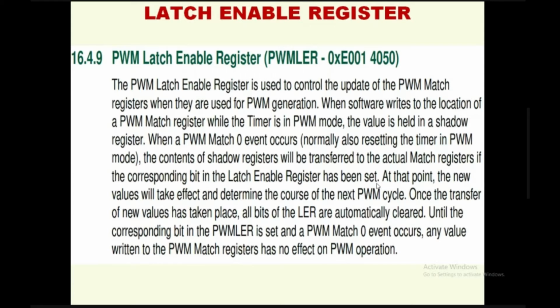That means every period only we have to change the duty cycle. So that is the only thing which we need to concentrate on. Within the period, we cannot change the duty cycle, as we all know very well, right? Within the period, it is impossible to change the duty cycle. If you fix the duty cycle for that period, that should be the duty cycle. Within that period, if you change the duty cycle register value like the MR5 value, that will never reflect in the waveform. So after the period is over, whatever value is in MR5 will be updated in the next period. That is what it mentions, right? So at that point, the new value will take effect and then determine the course of the next PWM cycle.